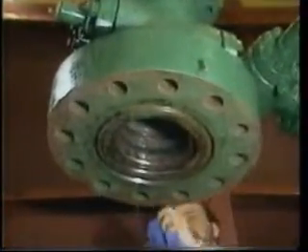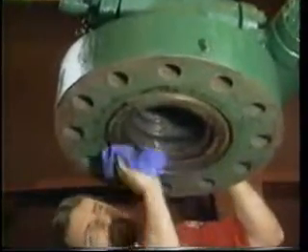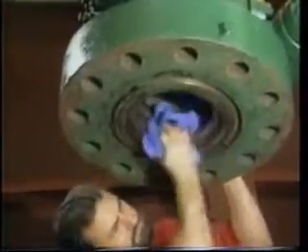Care must be taken to ensure that the seals are protected during drilling and installation in order to prevent damage or possible subsequent failure. Bowl protectors, sometimes called wear sleeves or wear bushings, are used during drilling and are designed to protect the entire bowl area of the casing head or casing spool from any damage caused during drilling or workover operations. The type of bowl protector required depends on the type of casing hanger and the bowl in use.